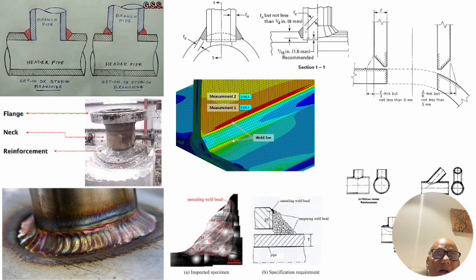So this is a portion, and both sides we are going to weld it, so it is not only this side of the weld that is highly stressed, the other side of this plate is also highly stressed because there is a fillet on the other side. And if there are any defects, because of gravity the weld is going to fall down, and there are undercuts or improper fusions, the reinforcements are not good, then we will have a worsening of this already high stress level with the bad impact of the weld profile.